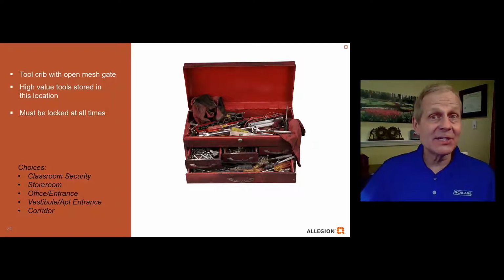All right, so if you selected storeroom, I would agree with you. Storeroom is locked at all times. Now, the only issue with the storeroom lock, if you have an open mesh gate, is that you're going to need some additional protective plates so somebody can't reach in with a bar or rod or a wire and pull down on the inside lever, because if they do that, they're going to be able to get into this tool crib.